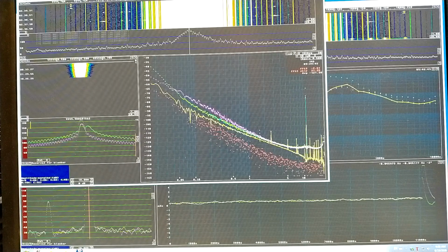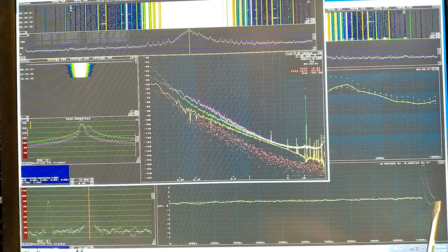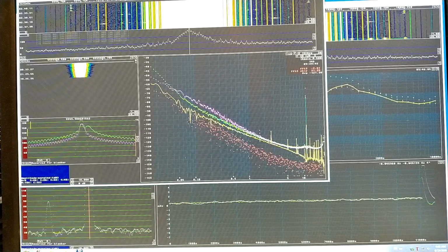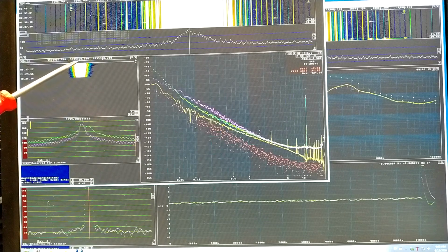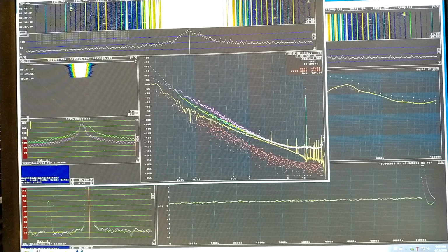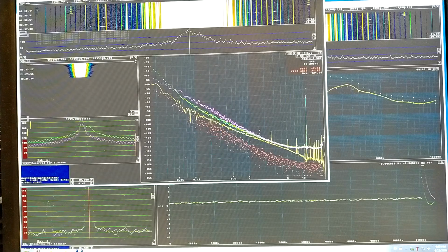So I have increased the fixed capacitance. There is a little screw for that. And now you can see how the frequency has changed and it's approaching the correct frequency. Now I have almost 2 volts on the capacitor diode. I will wait for a while to see what happens here after my change. And also maybe increase further. It's very slow, these processes, because of the long time constants.